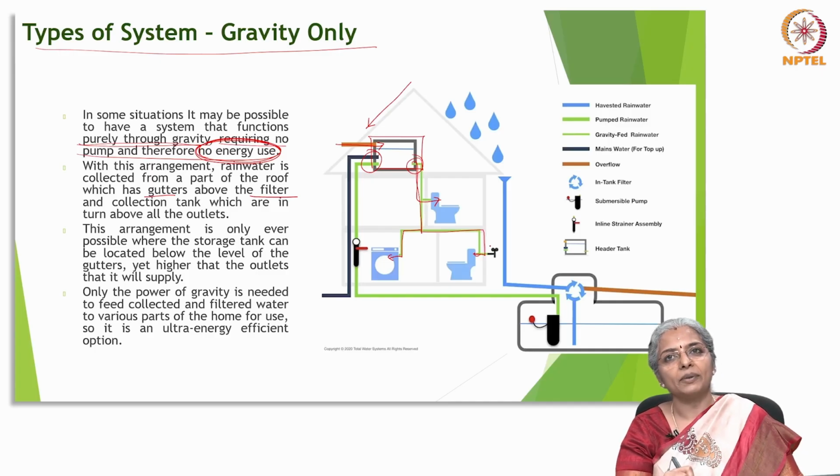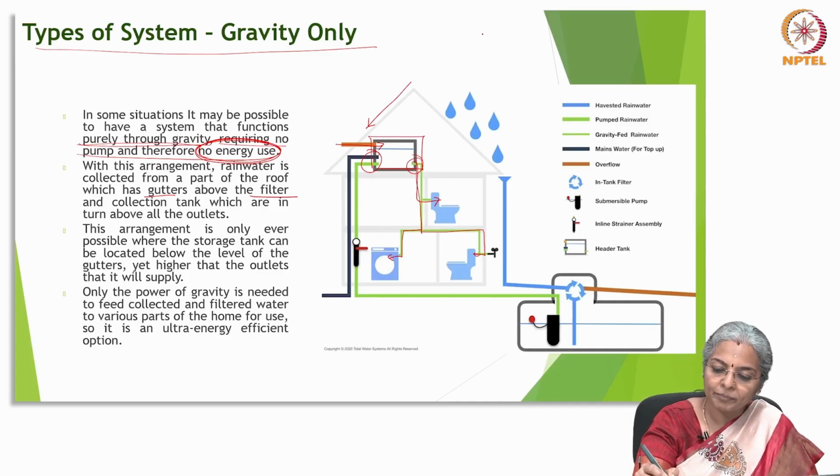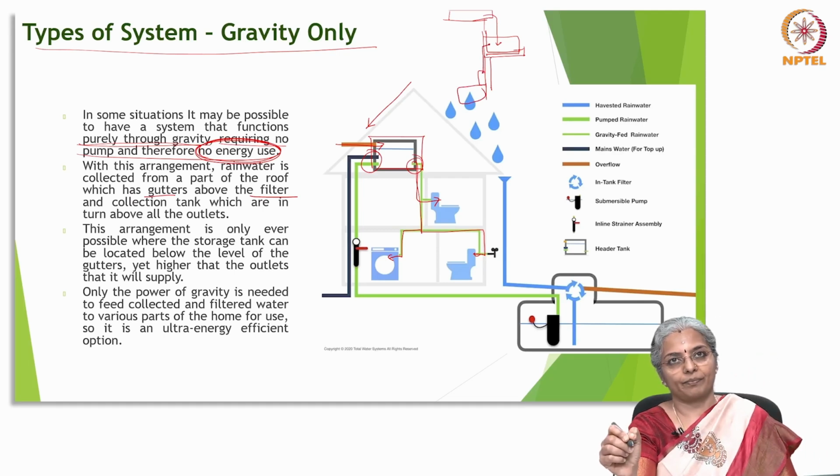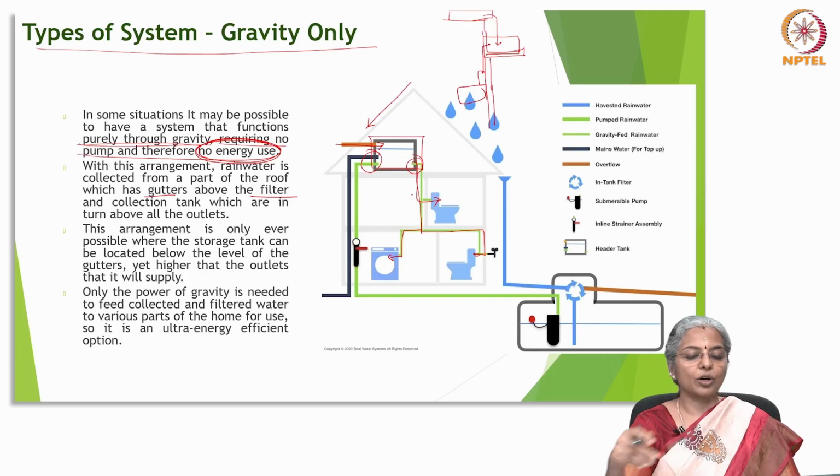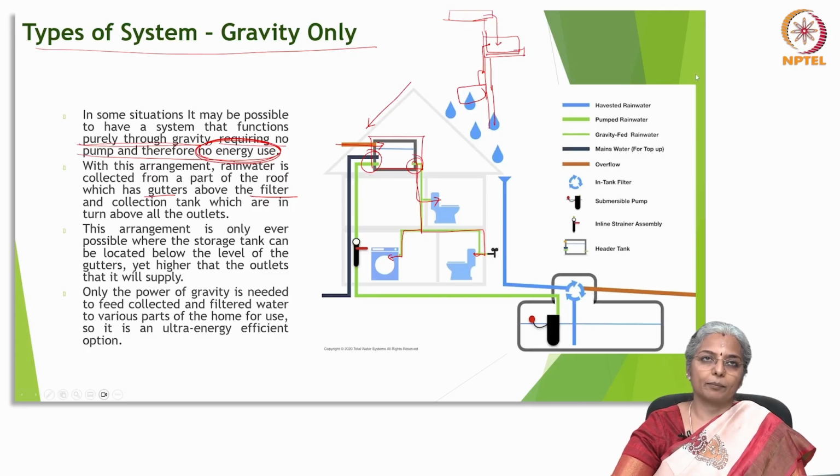A much simpler and rudimentary system can be, say you have a sunshade, you design a stronger sunshade and have small water tanks in this, and you have a larger water tank which will supply the water here. And what happens, suppose you have a WC here, this tank can be connected to the flush. So, a derivative of that is what I am saying, gravity only system.